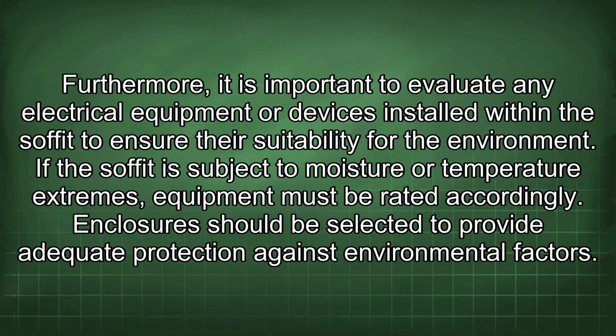Furthermore, it is important to evaluate any electrical equipment or devices installed within the soffit to ensure their suitability for the environment. If the soffit is subject to moisture or temperature extremes, equipment must be rated accordingly. Enclosures should be selected to provide adequate protection against environmental factors.